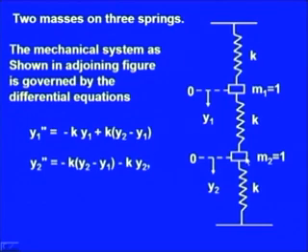Then there is a displacement y2 in the mass m2 at time t. So, the net resultant displacement will be y2 minus y1. So, for this lower spring, k times (y2 minus y1) will act upwards for the mass m1, while for the mass m2, k times (y2 minus y1) will act, and also ky2 will act upwards.